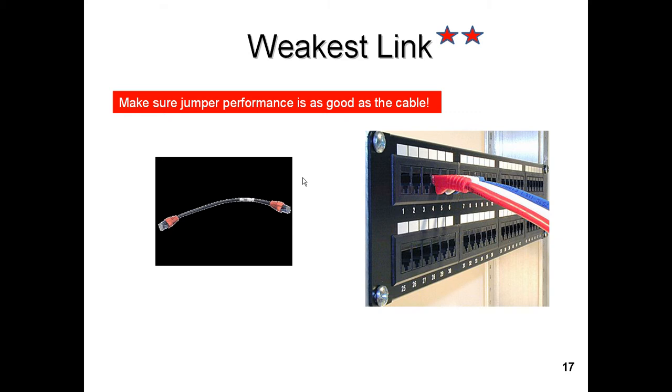the RJ45 sockets that we put on, we need to make sure they're put on correctly and understand that even though they work very well, what often happens with repeated insertions and connections in and out is that the little plastic spring clip loses its spring. It's happened to me many times in training classes.